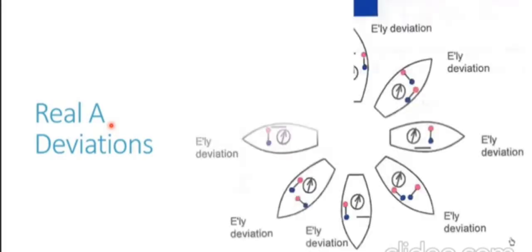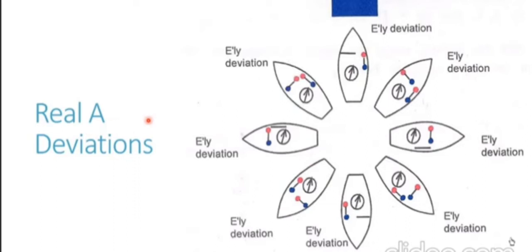Now this is understood by making a deviation diagram. For every coefficient, we will be making a deviation diagram like the one you see on the screen now. We have the ship on different headings: north, northeast, easterly, southeast, south, southwest, westerly, and northwesterly. So cardinal and intercardinal headings, the ship is shown on these 8 headings. And in each of these headings, we are going to analyze how these horizontal soft iron structures, an unsymmetrical pair of horizontal soft iron structures, generate the deviation which does not change. So we will first try to understand how these structures affect our ship, and second we will try to see how this effect remains the same irrespective of the heading of the ship.